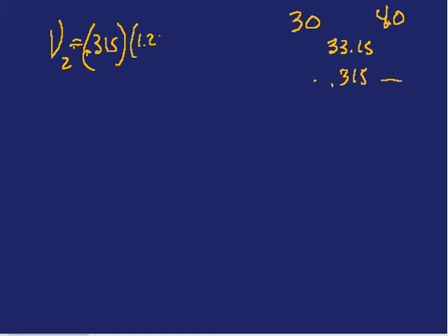So the volume at 2 is equal to 0.315, taking data from your table, 0.315 times 1.213 minus 1.653 plus 1.653, that's how you interpolate, is equal to 1.51. A similar interpolation on internal energy at state 2 gives you U2 equals 101.0.